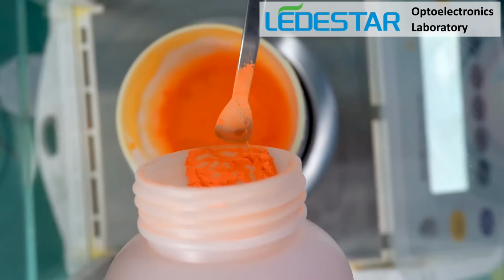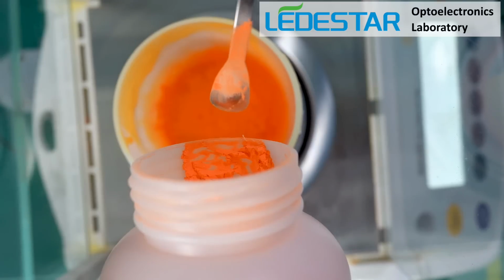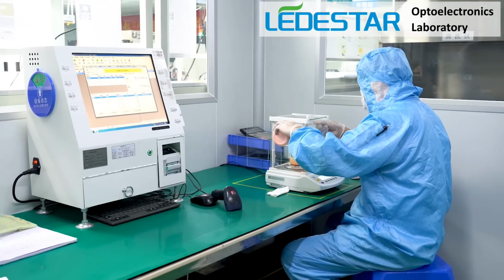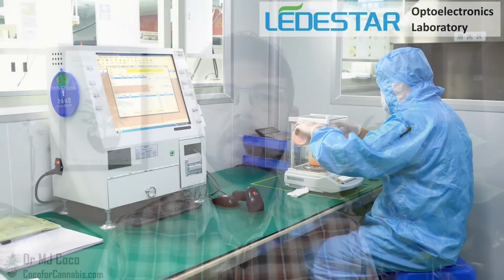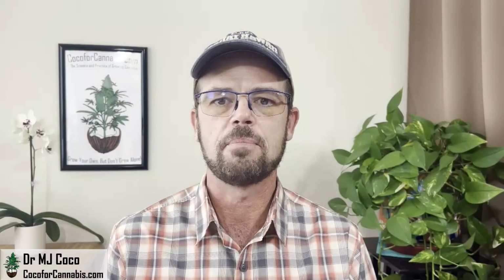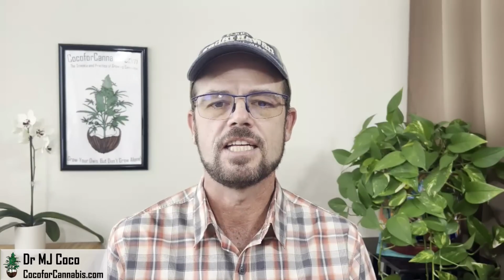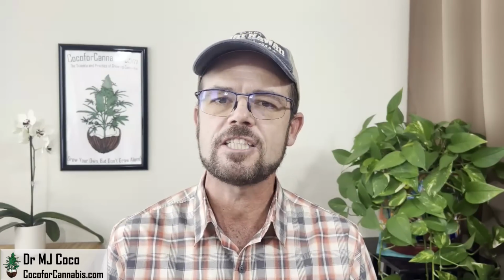But then there's phosphor and other elements added to the glue or epoxy that covers the semiconductor. The phosphor filters the light and distributes the spectral output. The specific blends of phosphor and other elements will determine the color temperature of the complete diode. And of course, when you filter light, you lose some in the process. So the specific blends of phosphor that different manufacturers use can affect diode efficiency. However, phosphor is only one of many factors that affect the efficiency of LEDs.